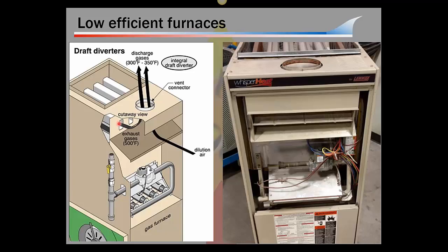I've got a burner producing 400 parts per million. That's a problem, and we could condemn this furnace. We should condemn this furnace if we can't fix that based on the CO being produced by that one burner. There's no reason to add them together and average them. This is an actual CO reading from each burner, okay?